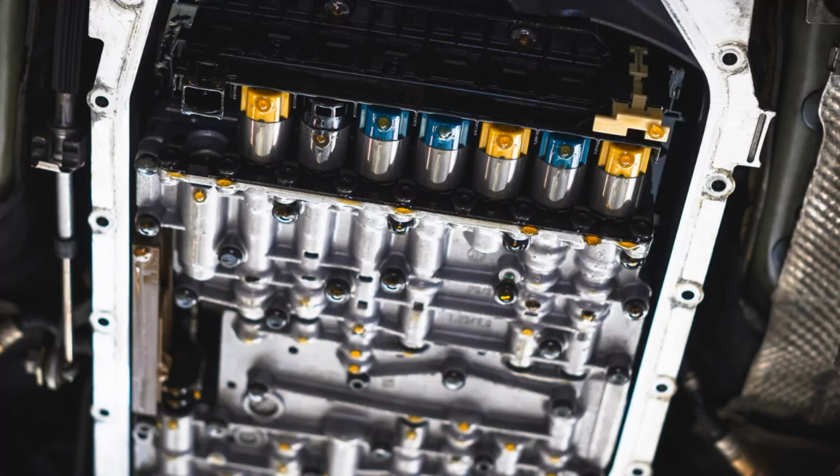Leaks. These occur as a result of worn or broken manifolds, plungers, and other components. When PWM solenoids are used, one of them may become loose. The control unit reads this information, recognizes the weakened solenoid as a malfunction, and as a result, its load is redistributed to the other solenoids, causing a certain overload.